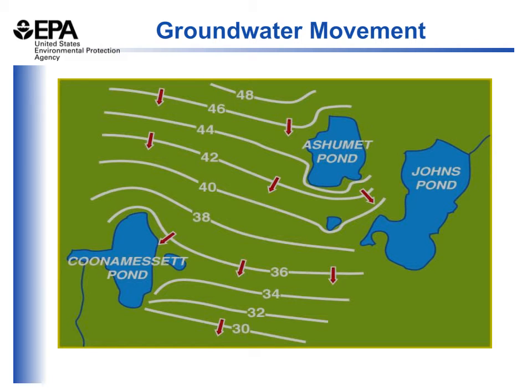Okay, so we know that groundwater is that water that completely fills the pore spaces or the fractures within the rock or sedimentary material below ground. And we also discussed earlier that this groundwater moves from areas of higher elevation to lower elevation. And it's important to know the direction of movement in order to know where the water is coming from that enters your drinking water well. The way we do that is with a water table map, as shown on this slide.